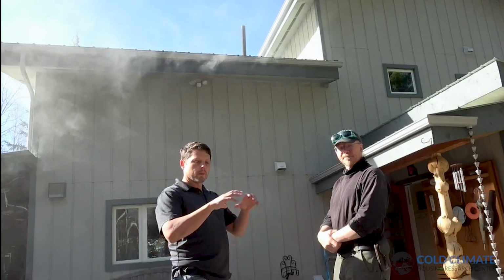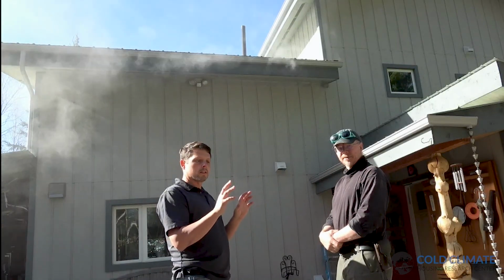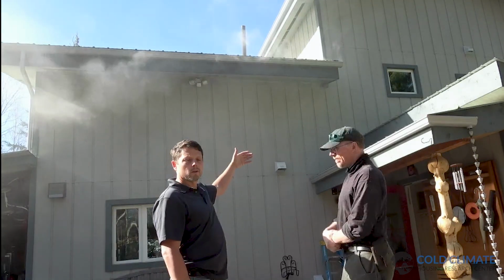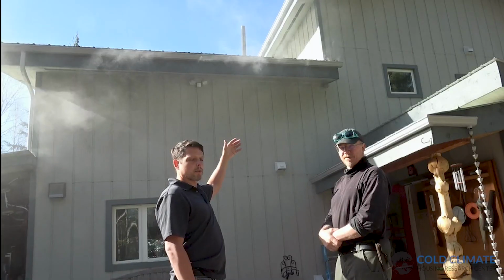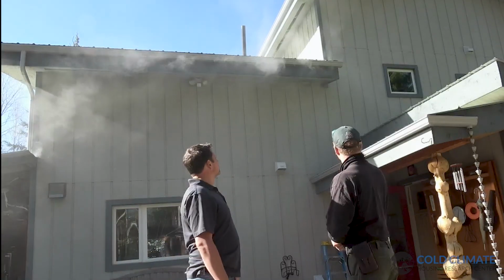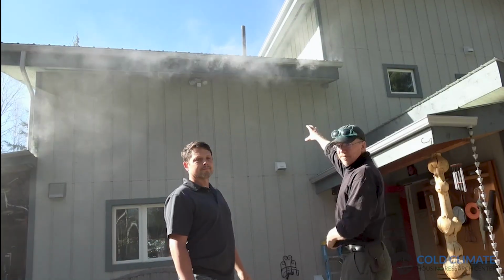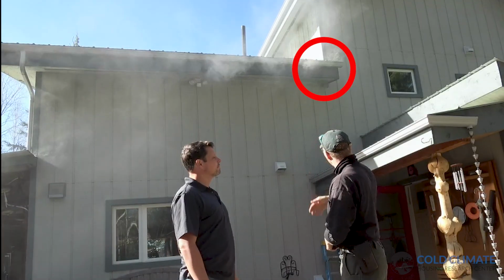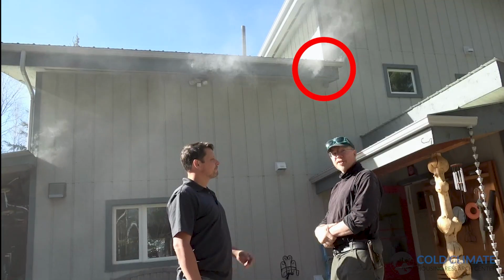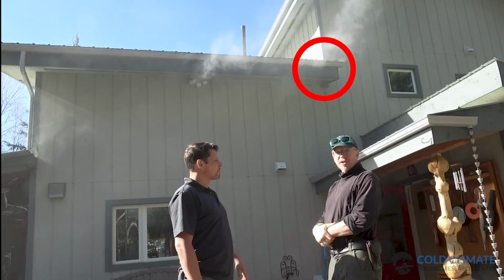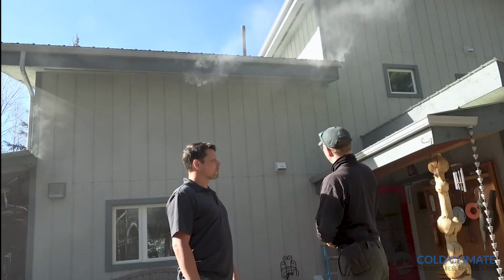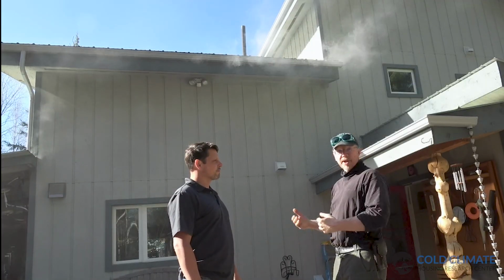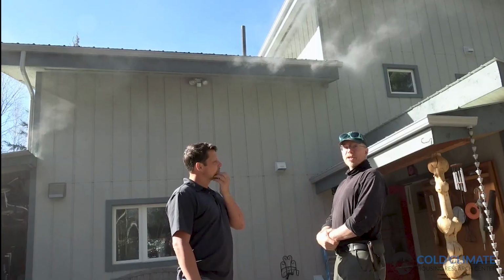We've got the home pressurized, and we're filling the zone with fog, and it's quite obvious where the air leakage is coming out of the home and where the air leakage pathways are. We have the fog machine in the master bedroom, right on the other side of this wall, and where that smoke is coming out of the roof is the master bedroom closet, and that's the area we had suspicions we had air leakage, and this is validating that we were correct. And now the next step is going to be to open up this area and investigate those leaks further.